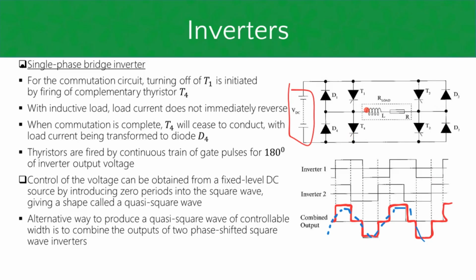So this is just a straightforward square wave switching method, so you're not going to get a sine wave this way. The one way that you can get a sine wave is by means of PWM switching, which we don't really look at for this chapter. So it's PWM and PDM. PDM is pulse density modulation. By increasing the density of pulses, you're increasing the average. And pulse width modulation is basically using the width of the pulse to change the average. Right.